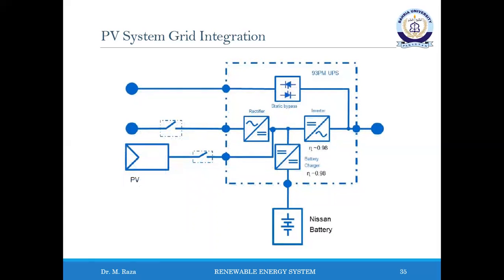The third topology alternative is to connect the PV array directly to the DC bus of the UPS. In this topology, there is only one DC-AC power conversion stage from PV source to the load. Theoretically, the highest possible total power conversion efficiency, about 97 to 98%, could be reached with this solution. Also, integration rate and power density of the system would be highest.